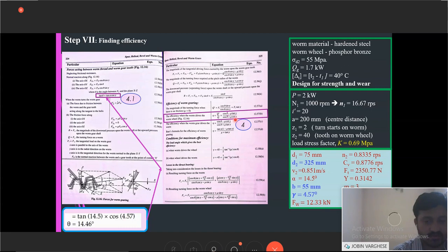We have to find out what is mu. For calculating mu, the friction coefficient, we can use the equation. The reason is that for a speed greater than 2.75, this equation should be used. When we see the velocity, we have calculated the velocity v equal to pi dn by 60. Before that, I'll just note that a parameter y is selected. Vr is equal to pi dn by 60. We have found 3.94 meters per second.